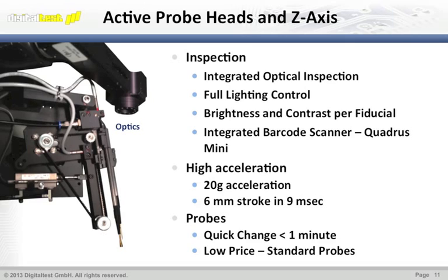This is really fantastic because it provides a belt and braces approach where if you can't get test coverage on a component for a reason, you can implement AOI onto the system. And then the probes, when they wear, they last for normally a month at full 24/7 operation. And those probes are in the order of $12 each. So very quick, low cost to change as we go through that.